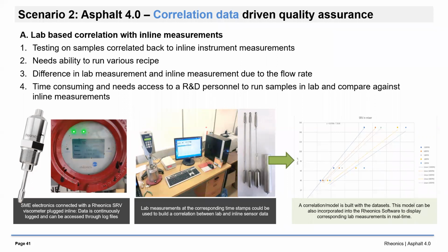But often what happens with a lab instrument is you have trend information and you are able to use a lab instrument quite well. It's very well established to check that you have got the right composition of asphalt, and it satisfies the different ASTM standards. So you have a good checkbox that says, this is the right asphalt, composition wise, flow property wise.